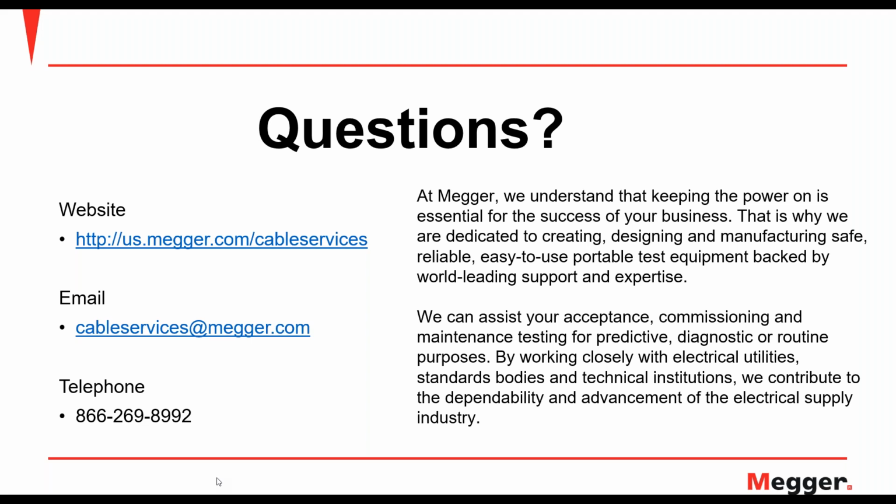Okay, yeah. So another good question here. As I mentioned, you don't want to perform tan delta on a new cable just due to those settling chemical processes that can affect your measurement. What I've seen is the recommendation is to wait about 1 year to perform the tan delta measurement, to wait for those processes to settle and subside, so that they won't influence your dielectric measurement. So after about 1 year in service, you can perform that tan delta measurement, and that can be your baseline to use for trending in the future when you perform your maintenance testing.